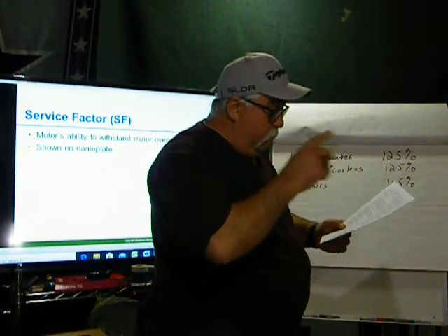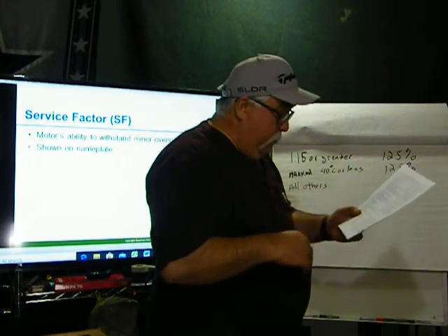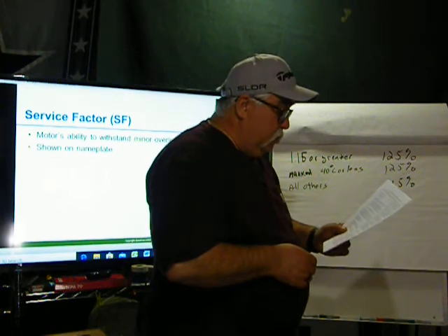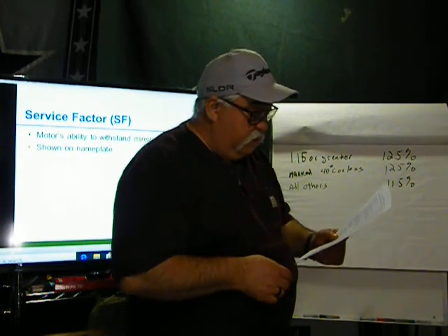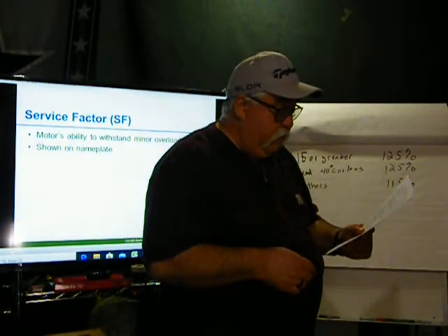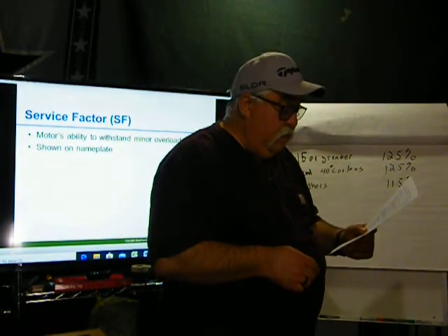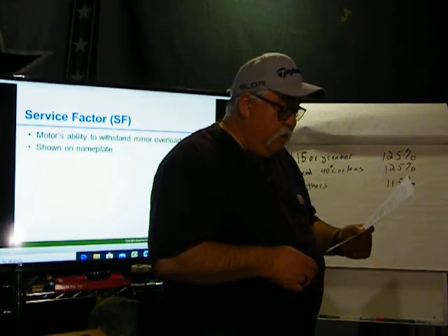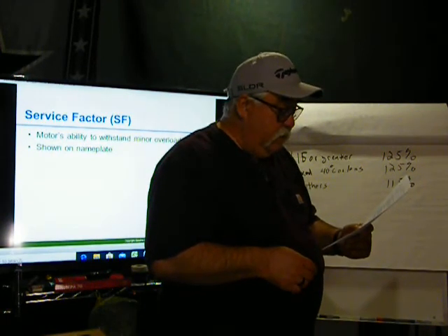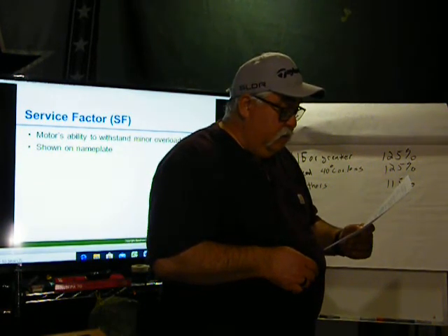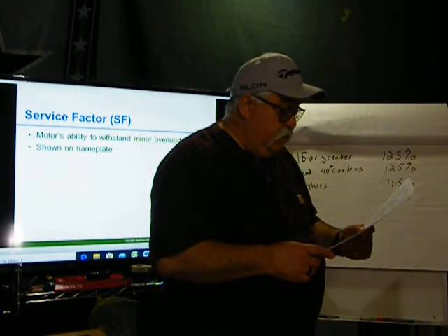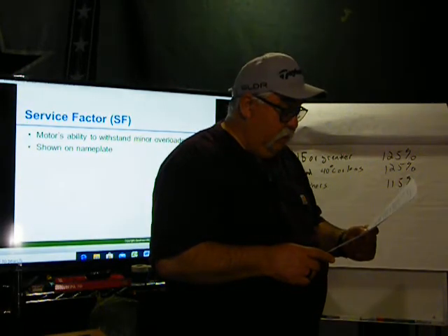And then it goes on further down, and you go to the same page. I'm on page 305 of the code. And then it says section C, overloads, where the sensing element or setting or sizing of the overload device selected in accordance with 430.32(A)(1) or 430.32(B)(1) is not sufficient to start the motor or to carry the load. Higher sensing elements or increment settings or sizing shall be permitted to be used, provided that the trip current of the overload device does not exceed the following percentage.